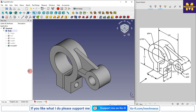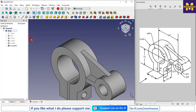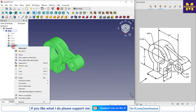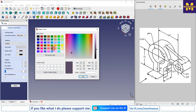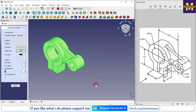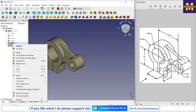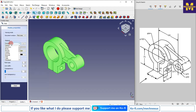So we have successfully converted this isometric image into the 3D model with the help of the Part Design workbench. Now we can give some random color to our part, or you can give your own color from here, but I prefer the chrome color, so I will go to the appearances and go for material and give the chrome.